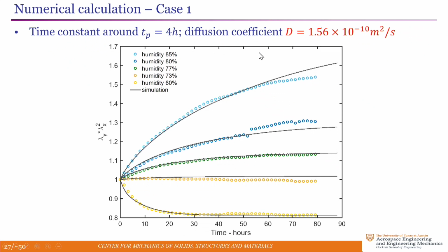The next one is to look for the diffusion. And now we go for just the water ingestion or egress. And the symbols are experiments. The solid lines are calculations of the volume expansion or drying with a single diffusion constant put in there and a value for the coupling between the flux and the change in the chemical potential, so the alpha R parameter. So we calibrate those from there.